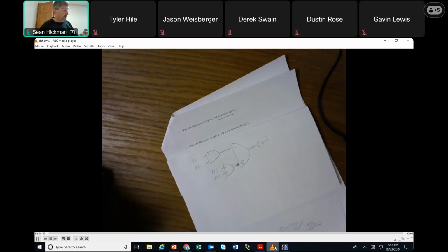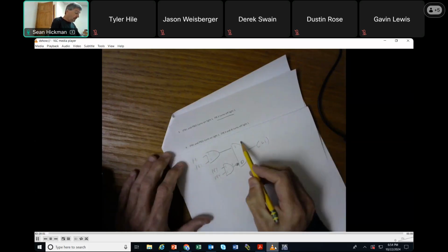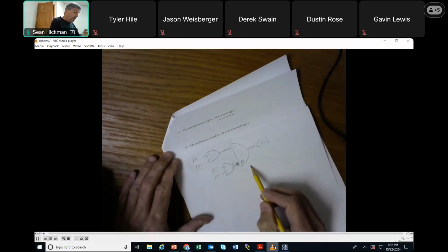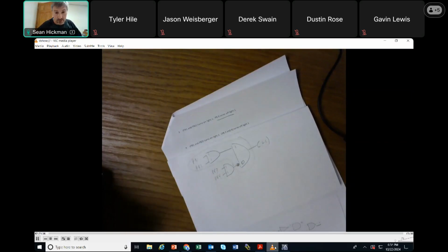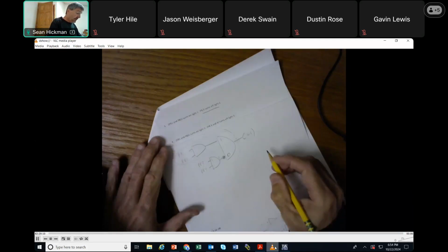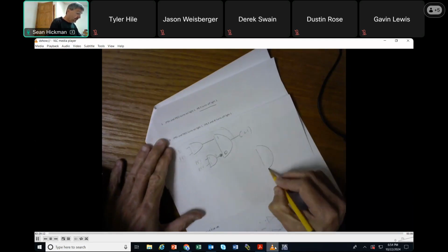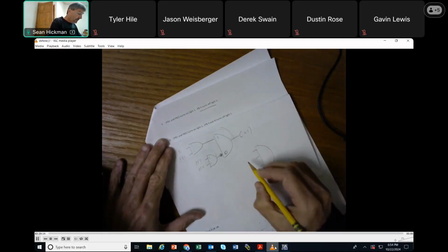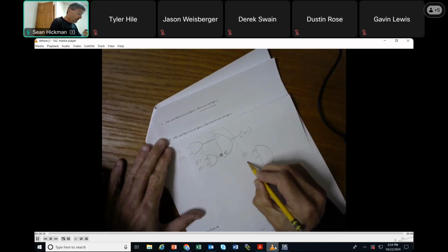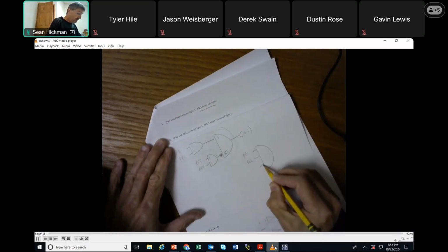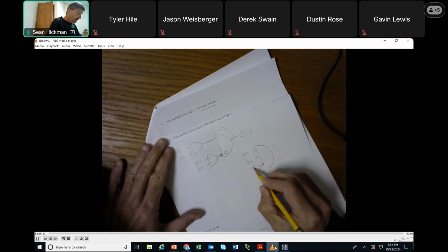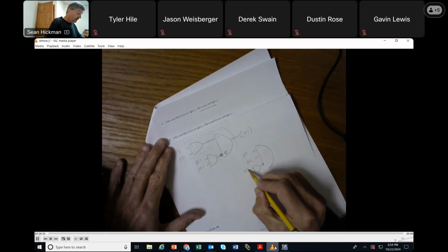Okay? Now, if you have 2 ANDs in series like that with nothing in their way, you can simplify this to PB1, PB2, NOT PB3, and PB4.